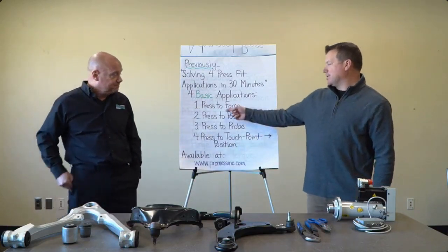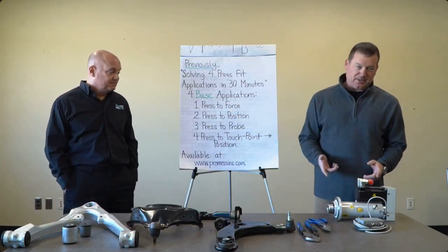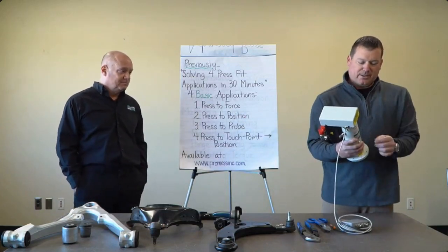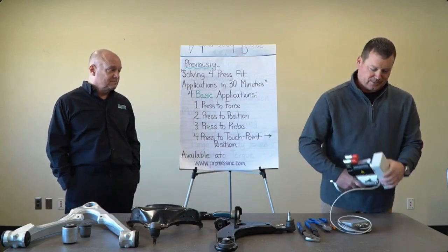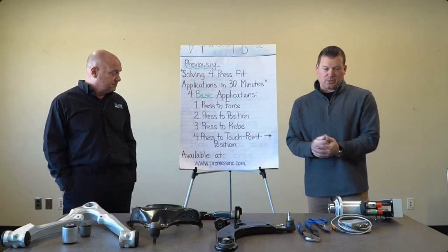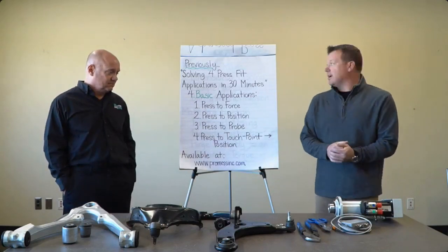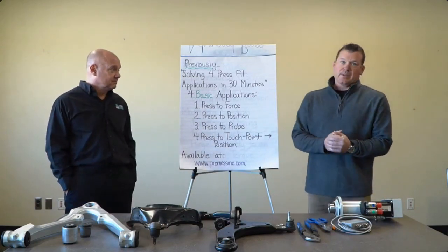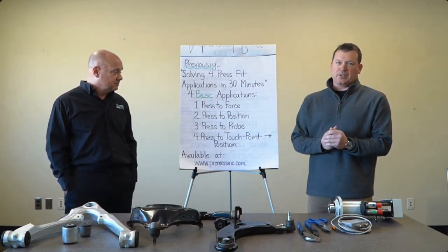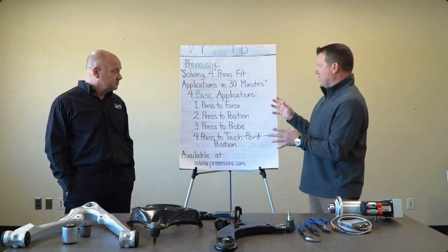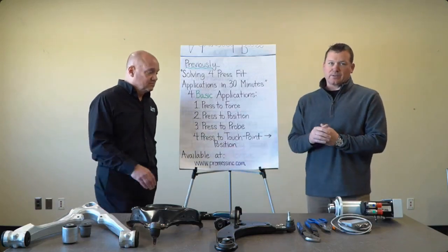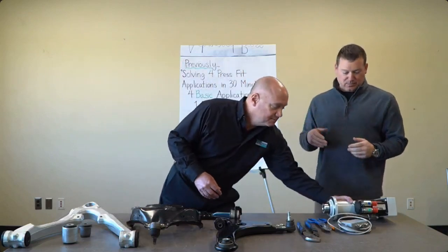So one was press to a force, which basically means we're using the integrated load cell in our servo press to control through a force. Like bearing pressing, anything that has a press fit that presses to a shoulder, generally you're going to use a press to force type program. The other one is press to a position. Keep in mind these are all the basic applications, and as Glenn said earlier, we're going to focus more on the advanced as we get into this webinar.